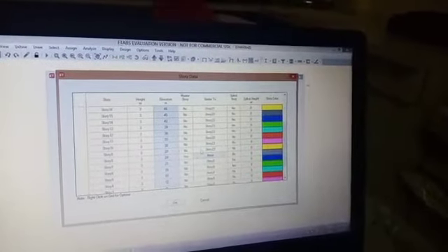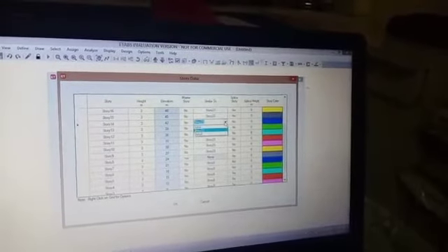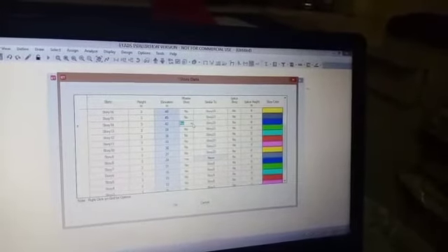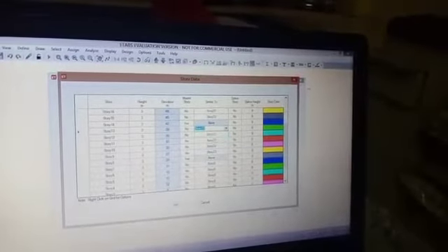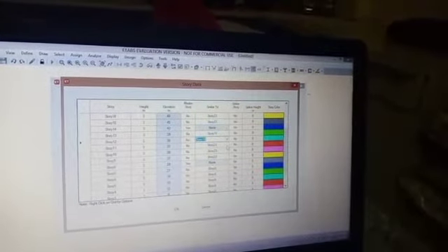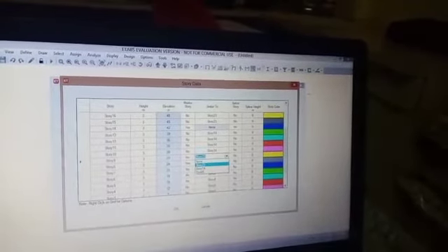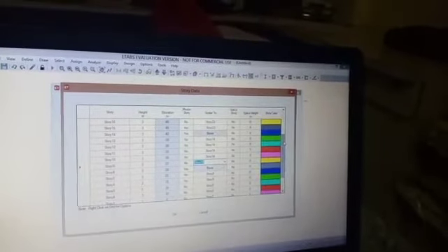Now choose another story between 9 to 14 and change it as the master story. And change the remaining stories as similar to story number 14. Then 15 to 19 next.